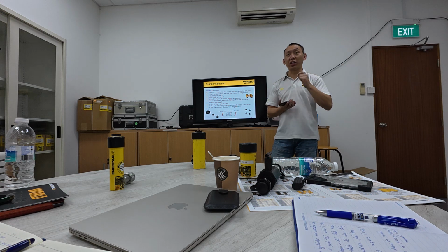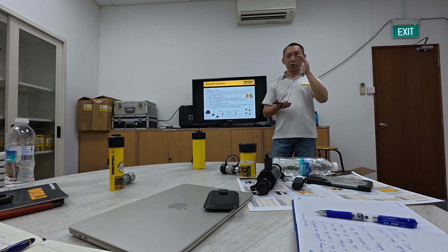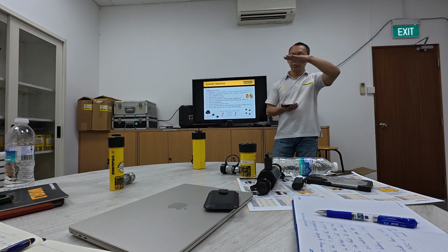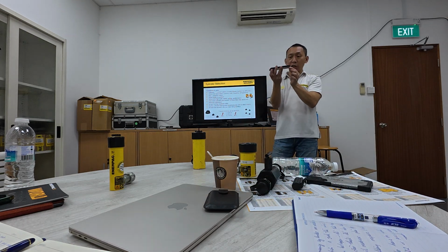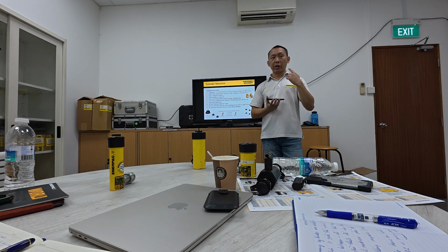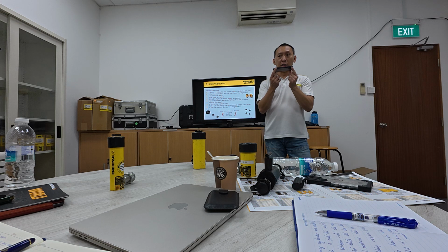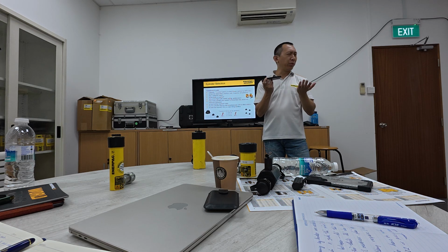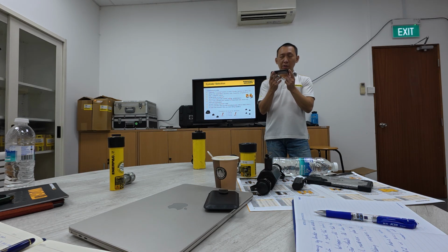So it depends on how critical the job is. If it's not critical, flow control valve is okay. But if it's a critical job where the customer requires, let's say, 1% or 5%, where this point cannot be higher by more than 1%, that's where we can use a different type of control, a different pump. We have products like the split flow pump, the SFP, equal flow to each point. The accuracy will be higher, I think around 3 to 5%, but it's still based on flow.